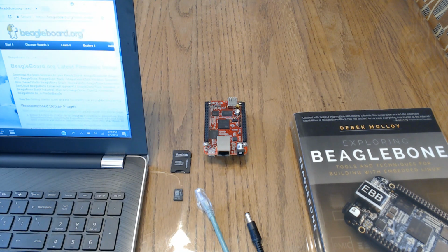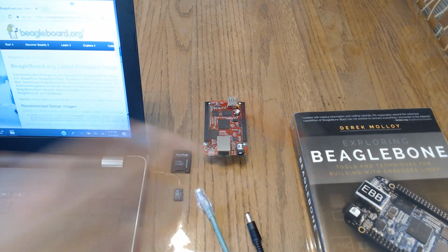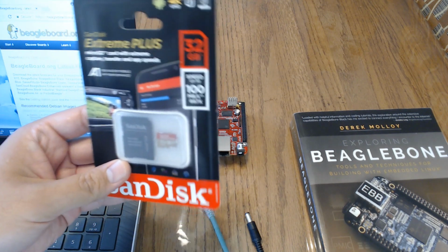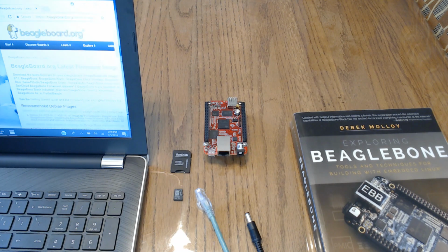This version is the industrial rated version from Element 14, and of course it's not black, it's red. Most of them look like this. You're going to need an SD card with at least 4 gigabytes of capacity. If you have an SD card with more capacity than that, that's perfectly fine, and it's actually better for reliability purposes. And remember that all SD cards are not equal. Probably the best combination of reliability and price are the Samsung and also the SanDisk SD cards in the 16, 32, and 64 gigabyte capacities that are commonly available right now.